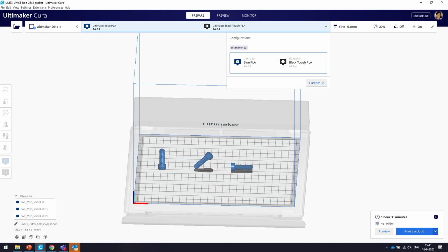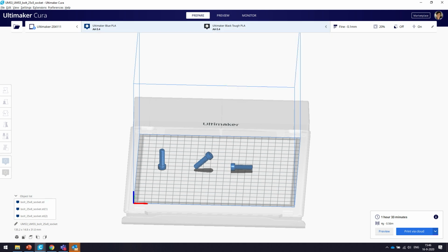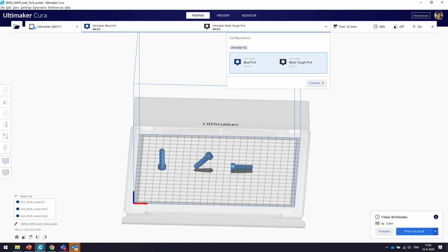Great. So now let's continue our exploration of the 3D control software aspects, moving across the top now to the section to assign extruder types and materials. Yes. So Terri-Ann, you can show how that works. If you press this, you have to change your configuration, right? When you want to print something by default in Cura, it will always be generic PLA when you start it. But when you add the printer and you connect to it and you open this menu, it will immediately give you the available configuration that is currently on your connected printer.